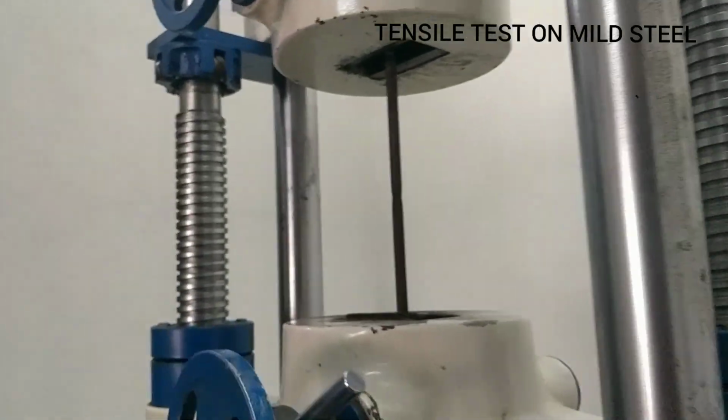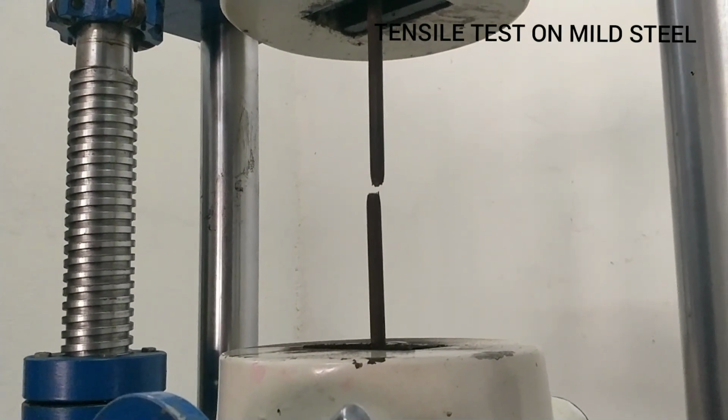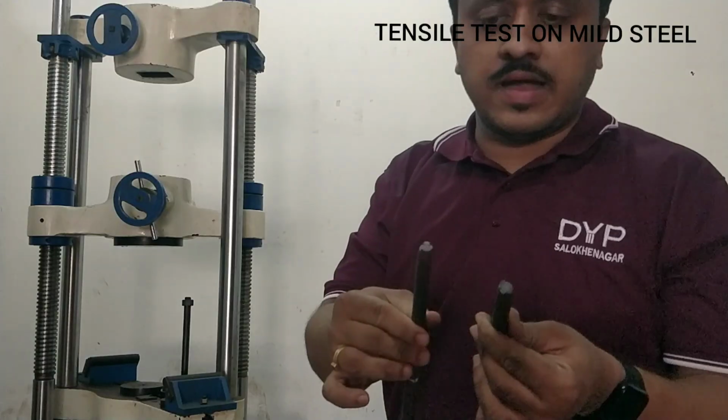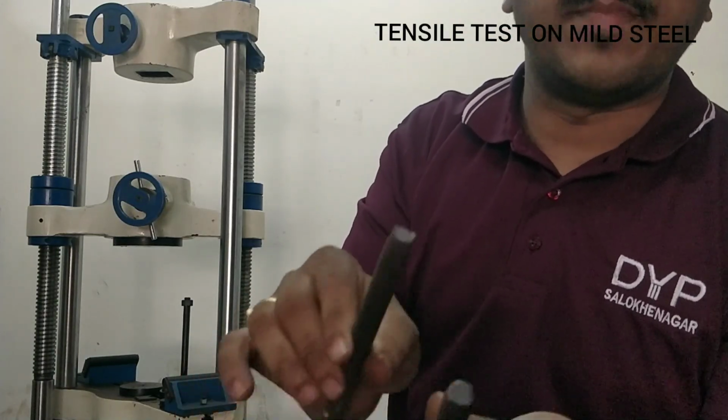We'll see, and the bar is broken. Now you can see the bar has broken successfully, and it has broken in the form of a cup and cone shape. You can see the cup and cone shape here in detail.